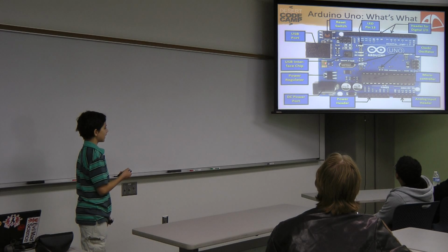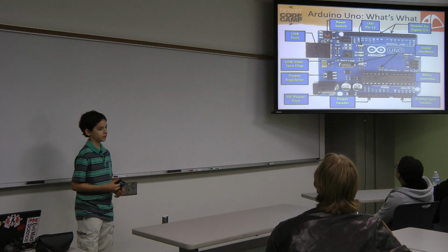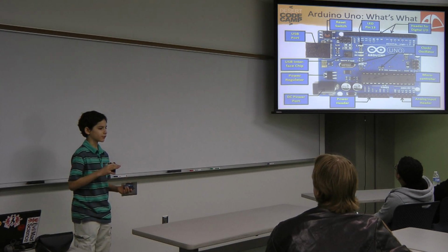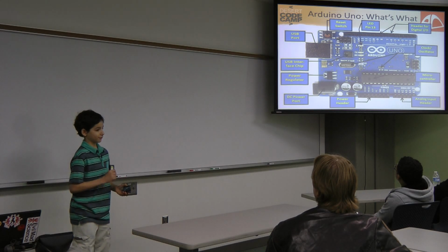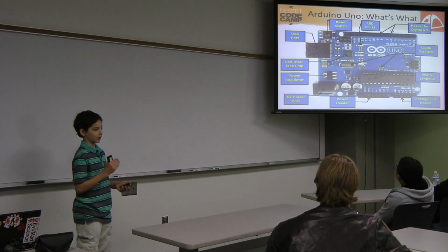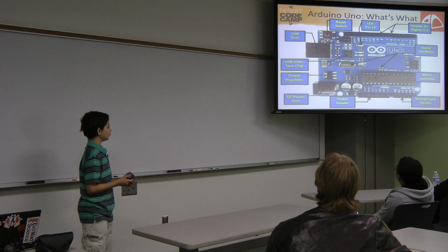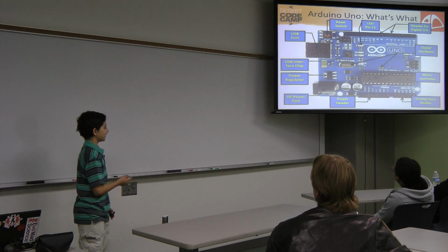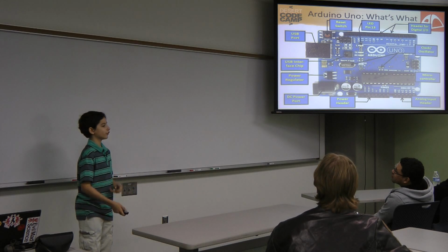That little gold thing there is a polyfuse, or self-resetting fuse. The way it works is it will allow up to about 500 milliamps to flow, which is about what USB can provide. It's only for USB though. Then it gets really hot and blocks the current from flowing, because it's a temperature controlled resistor, or a thermistor. Say you maybe short out power and ground, or you do something that isn't good. That'll heat up and cause it to block the power flowing so you don't damage anything.